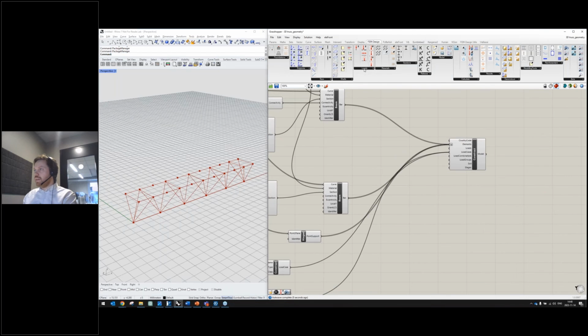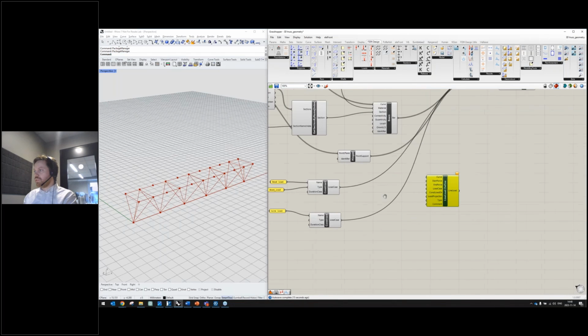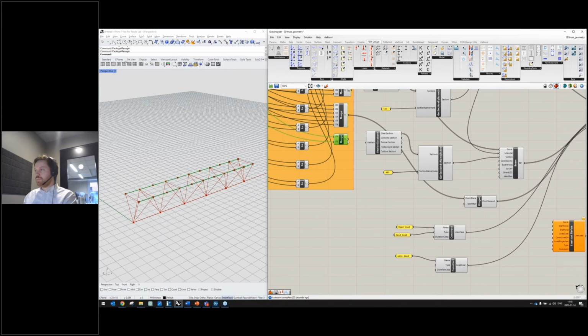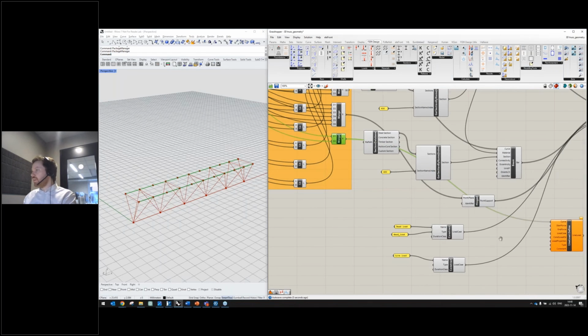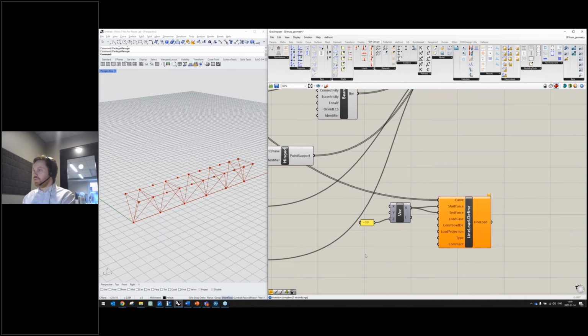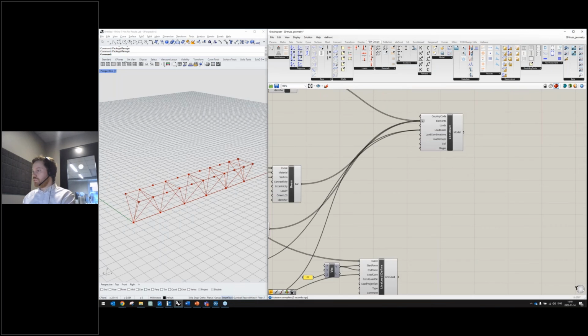So let's add a line load. I go into line load define, and I want a curve, starting force, end force, and a load case. So the curve, I have these two lines that I want to apply here, and let's say a value. It should be a vector, the start force and end force. So let's search for vector, and maybe I want just minus 30 kilonewtons in Z direction. I use that as a start and end force, and a load case. Let's put that into the live load case and add that to the model.